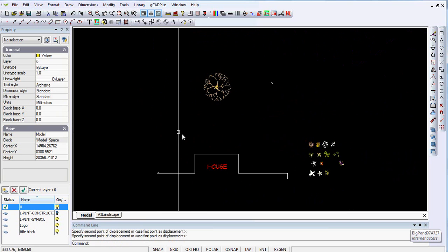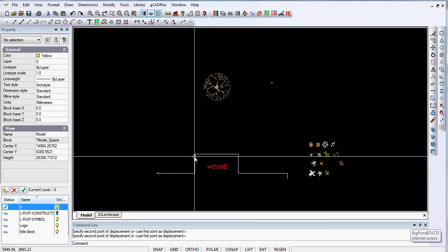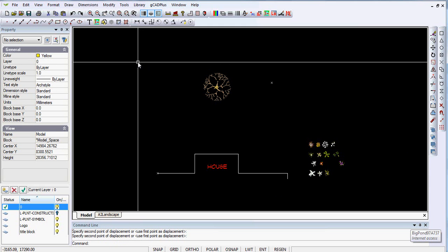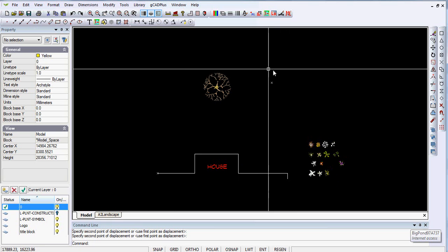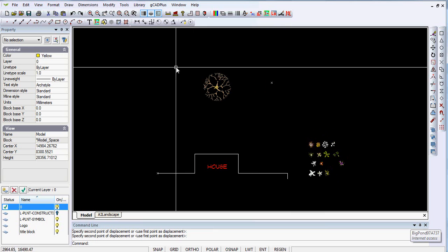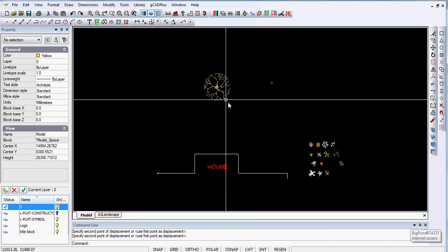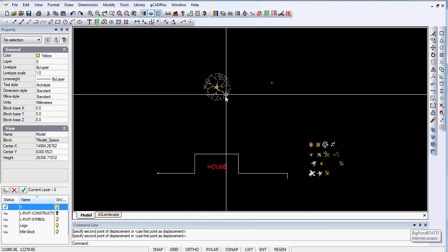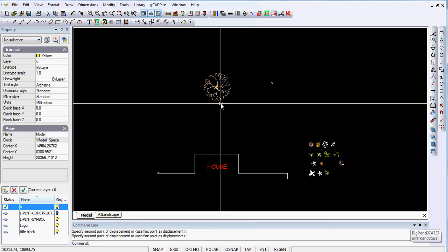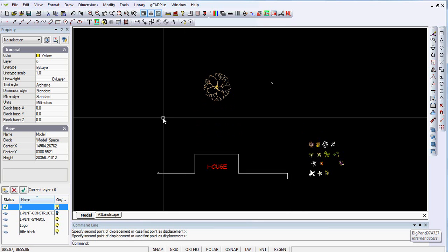Perhaps the next step would be to locate the back boundary across here. We might take a measurement from that corner up into that corner, and from here into another corner. That would give us the back boundary of the site. Well, imagine that the back boundary sits on top of a sloping area which slopes down into this area, and we need to build a retaining wall through there which will encompass that particular existing tree. Then we can fill in the design in the area around it. So that's how to accurately locate an existing tree on the site.